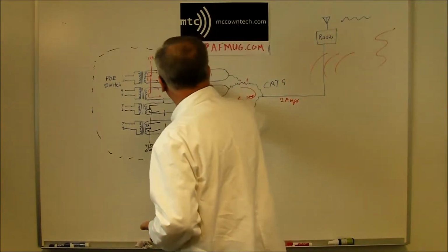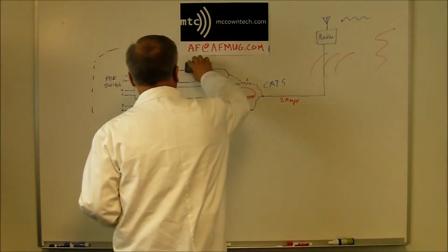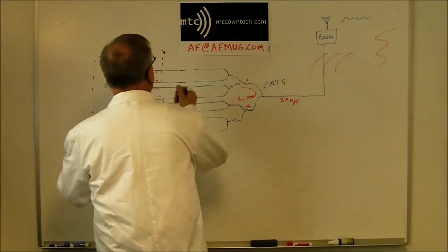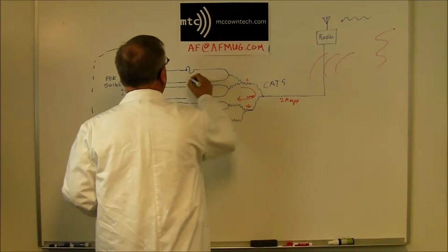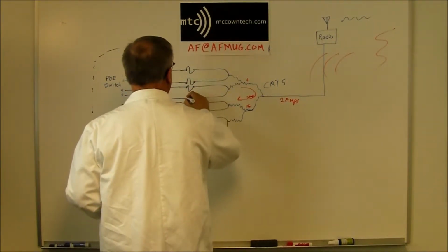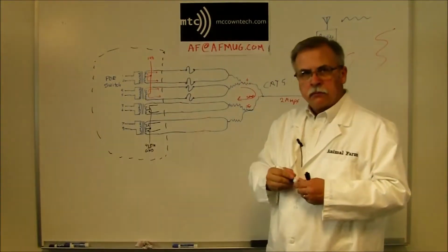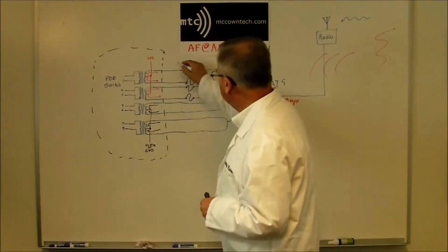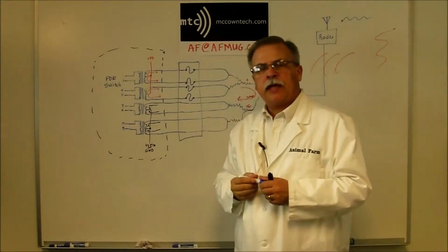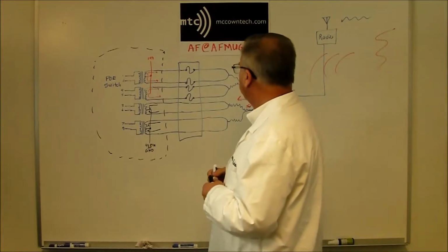Well, that's pretty easy. You have a really old-fashioned device. It has a symbol that looks like this. You got a fuse, a PoE fuse. Put that in line. Make it replaceable. How do you know if it's blown? Well, put some LEDs on it.